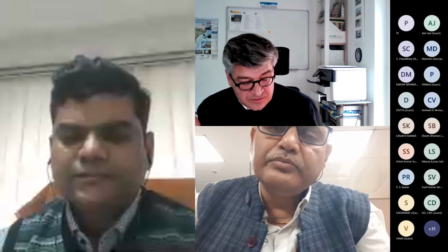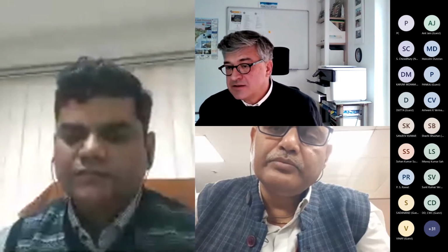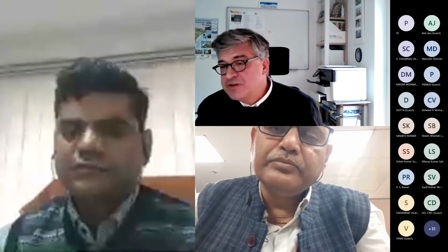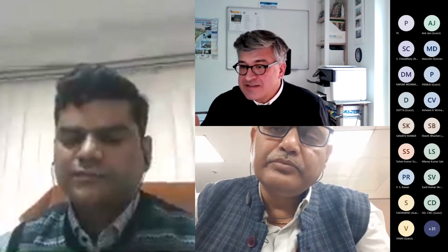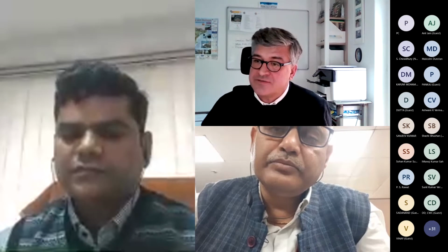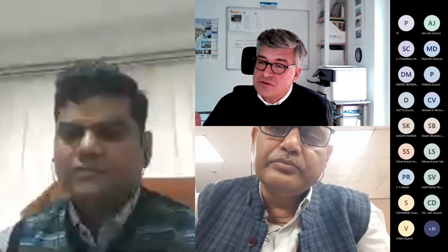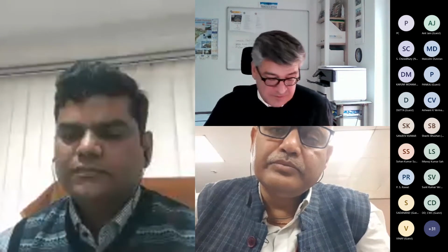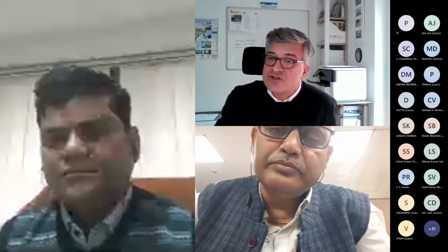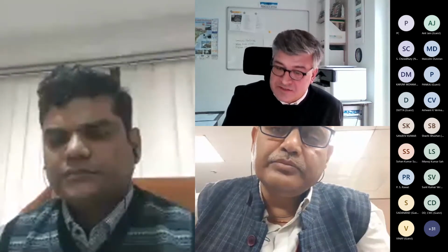Yeah, the reduction of the maximum size of aggregate in RCC should not be a matter of discussion anymore. It's really necessary in all kinds of RCCs. We need to fight against the segregation problem, and the reduction of the maximum size is the solution for that, in addition to the workability and the consistency.